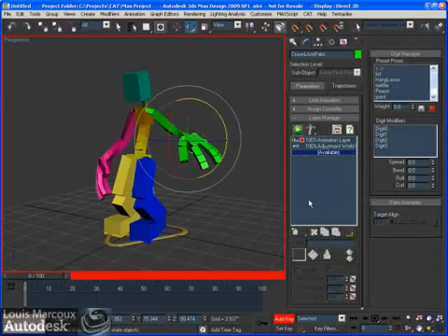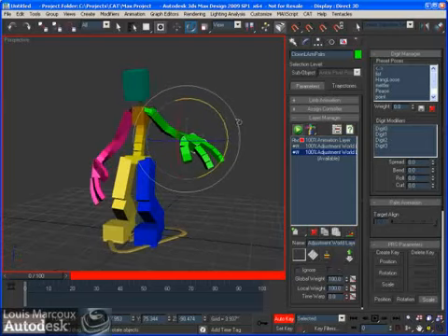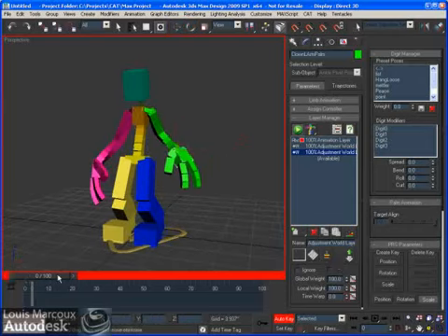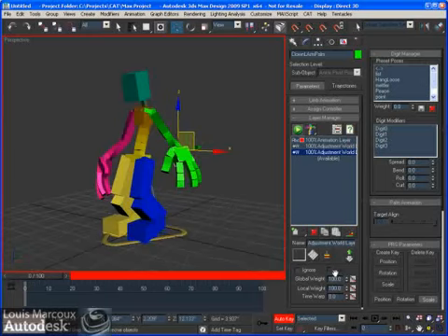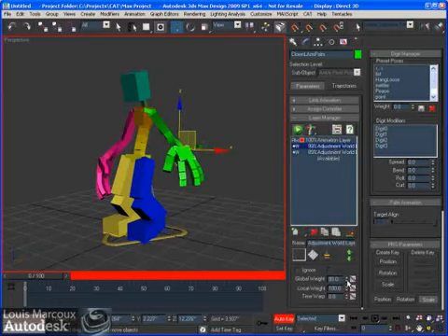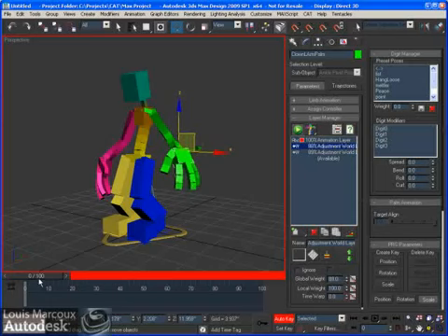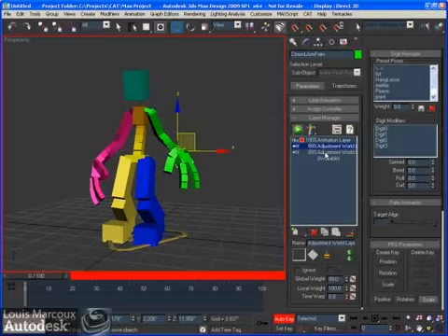If I go back here in the available slot and adjust again, I can create another world adjustment. I can say, well, I want that to be like this and like that. So now what I've got is two offsets on the overall animation, and I can blend in the effect of the world adjustment layer to have my final offset available to me based on the first animation layer. So I hope it's clear for the adjustment layer.